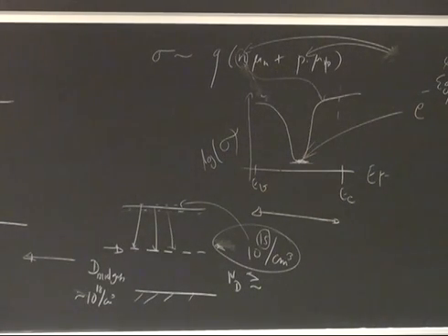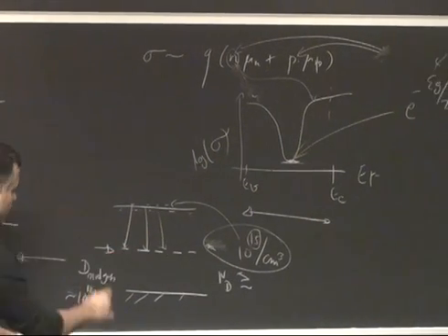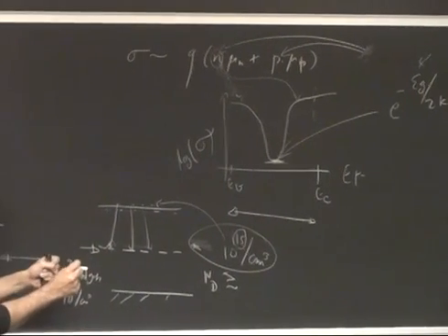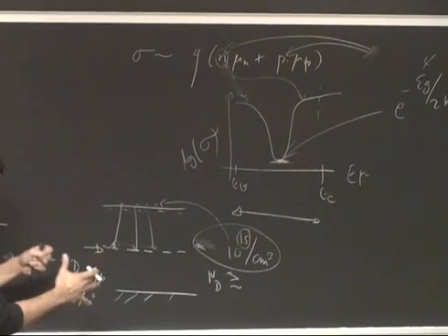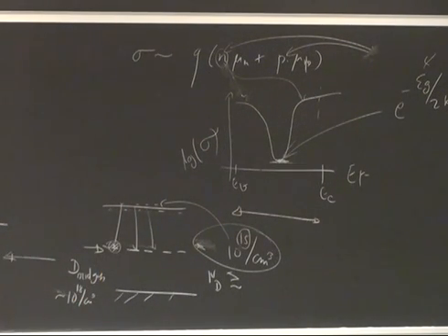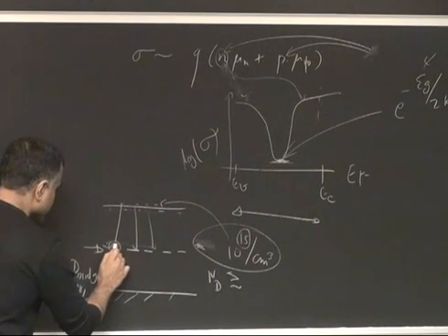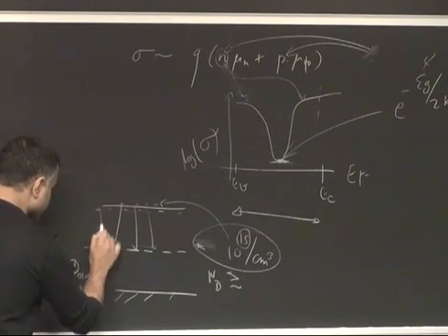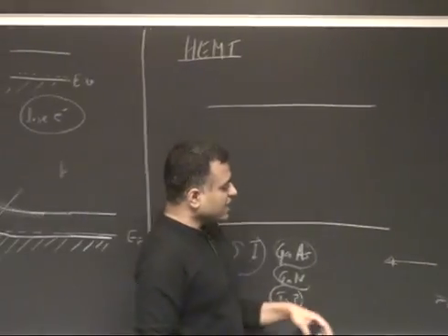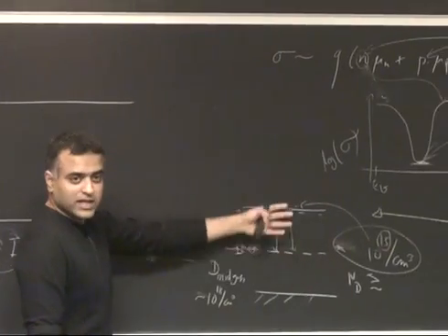Okay? And when they are here, they are localized, so they cannot hop from one site to another, so they get stuck at the dopant level. The wave function of the electron is very small. These are deep level states, very small and localized. It cannot move, and the temperature is not enough, because it's so deep, it cannot be kicked out either. Does this make sense? So it cannot be ionized, so it becomes immobile. You basically remove the carriers. And you can do the same thing for holes, but it's typically done for electrons, these deep levels.